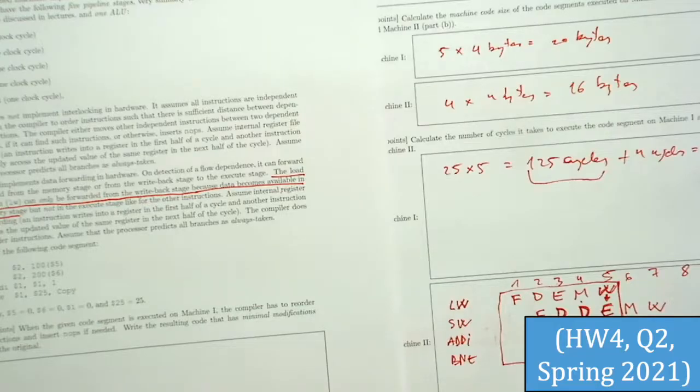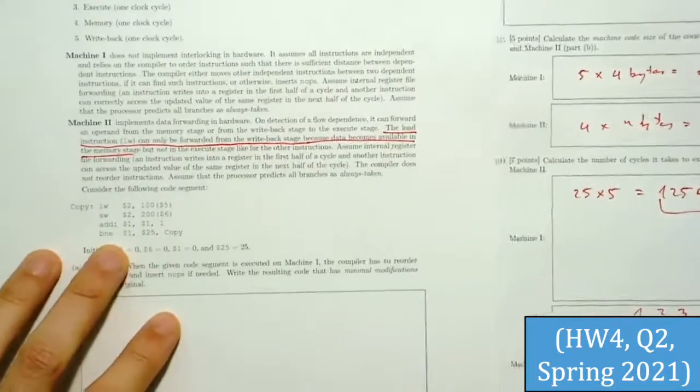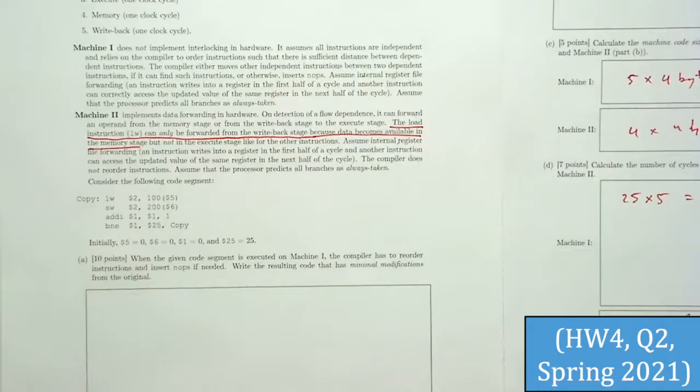It wouldn't work for me because I wouldn't have left the decode stage because the valid bits aren't 1 yet. So there won't even be a situation where I get the data forwarded from memory to execute because I wouldn't be in the execute stage yet because the valid bits aren't set yet. You see my problem? If it works in the book, it has a hazard detection unit or whatever it's called, then it works. But with scoreboarding, for me it doesn't.